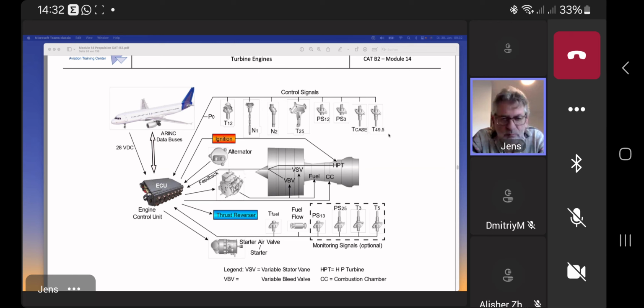Minimum two reasons. On the one hand, the designers, the constructors of the engine define the EGT limit as a temperature where we run the risk that the engine gets destroyed. First task of the turbine is to survive, before it extracts any energy. I told you this already. Therefore, EGT is limited. The engine should not be destroyed because it costs a lot of money. So therefore, EGT measurement is very important.